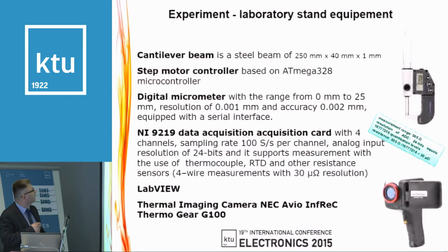So we have a cantilever beam of this size, a step motor controller, a micrometer with a serial interface, and a National Instruments data acquisition card. We used a four-wire connection in order to measure the resistance of the sensor. Of course, LabVIEW is the data acquisition program, and additionally, in order to see the temperature distribution on the cantilever beam, we used a thermal imaging camera.